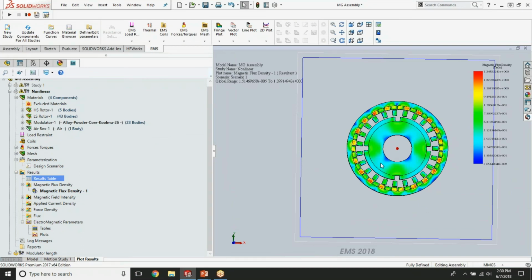So it's very important to check: if the specific design, the air gap length and the distribution of magnets are such that when using linear simulation you get very saturated field results, then it would be a very good thing to go back, change to a nonlinear material if you have it, and rerun everything to get much more accurate torque results.